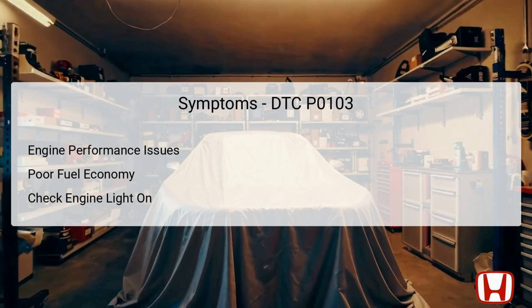Additionally, drivers may notice a decline in fuel economy as the engine struggles to maintain optimal efficiency with inaccurate airflow measurements. Overall, these symptoms underscore the importance of promptly investigating and addressing the underlying issues associated with DTC P0103 to maintain vehicle performance and reliability.